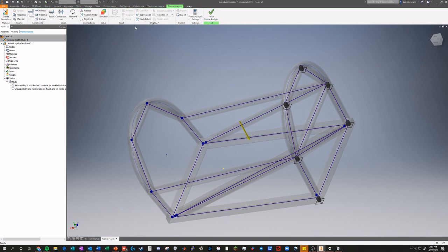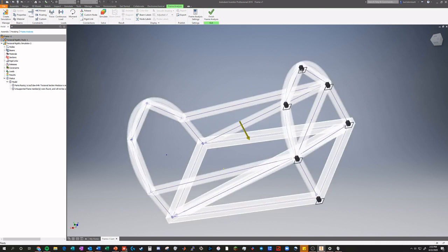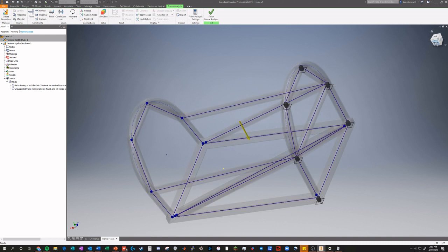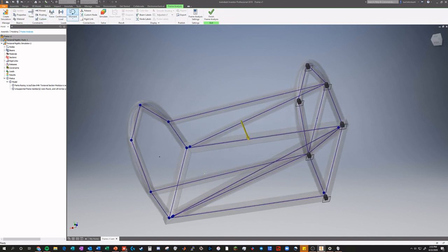So basically what you're going to notice that I do is you'll set these constraints, and then once you're done setting your constraints, you can apply any sort of load you want. So your options are going to be a force at a node. So for example, you can apply it along an axis, I guess. Or no, this will apply a point load anywhere along that axis.